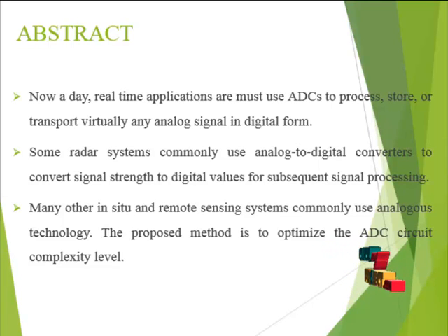It reduces the head room, and the traditional approach of cascode amplifiers to generate sufficient gain is improved in the CMOS process. Although we still require large power and complicated frequency compensation techniques, we have achieved a high effective gain with a low gain op-amp. We have also considered correlated level shifting and parallel use of amplifiers, and zero crossing based circuits.